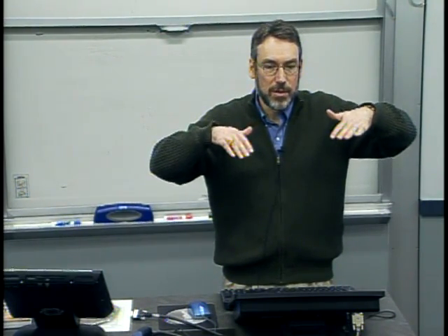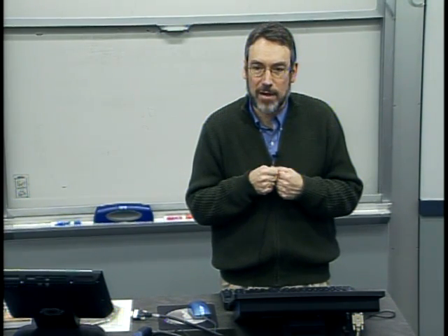So in this picture, we're starting out here with the silicon in white. We add or create a thin layer of silicon dioxide in this picture. Now there's lots of different processes, and many of these are discussed in more detail in May and Spanos, for creating silicon dioxide. One is deposit on the surface. The other is to actually, quote, grow a silicon dioxide layer.